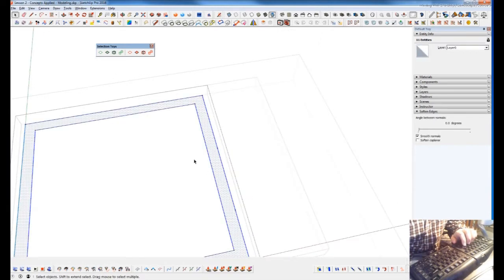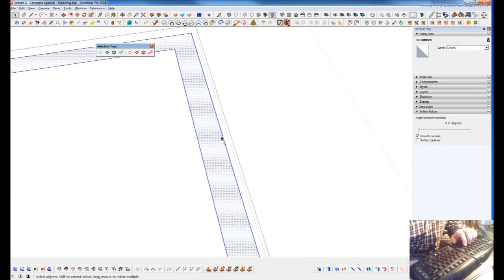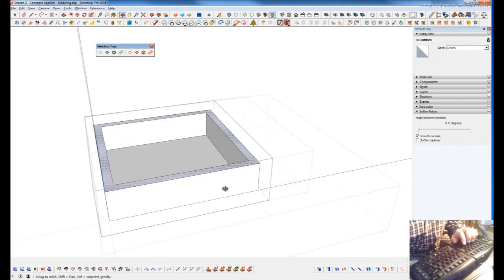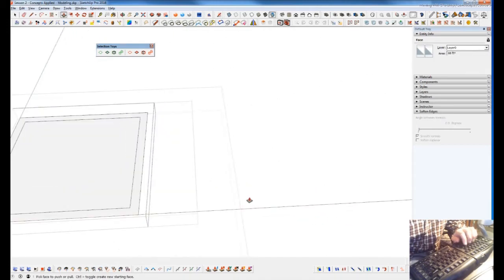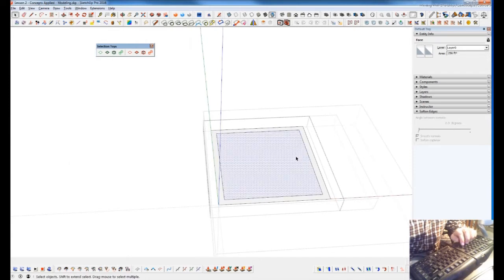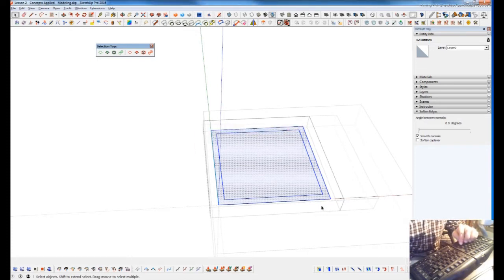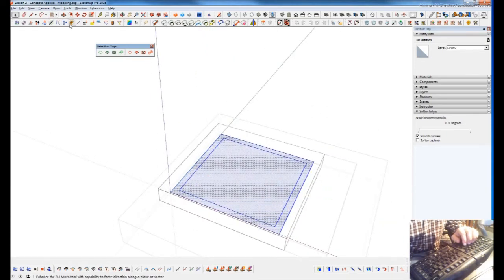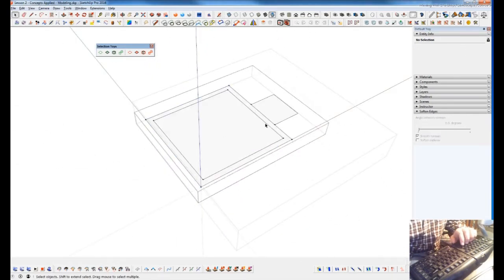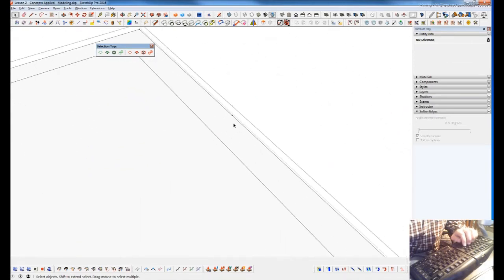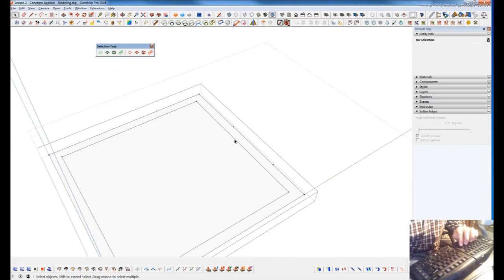And now we get in here and we can see we've created two extra. If I mark vertices, created two extra ones. And if I pull this now, I have these extra lines here. So very quickly, now I can go through there and select all of those and hit Alt-Shift-V, and it will remove the extra ones without me having to go up here and look at the toolbar. So I can do that while I'm in cleanup mode on the fly and very quickly and easily.